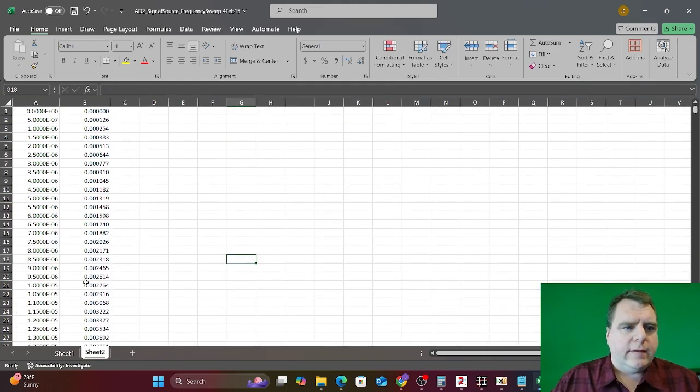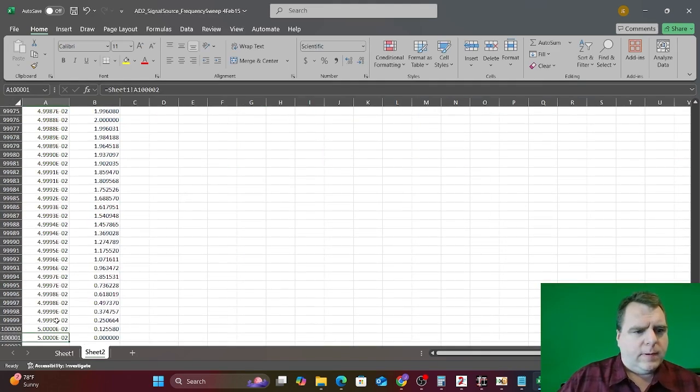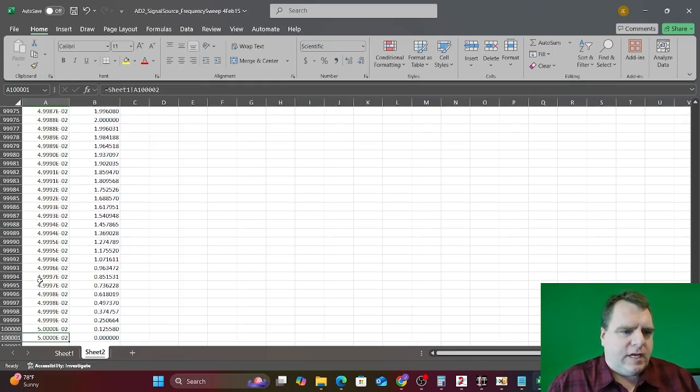Then when you look at the data here in the time column, you'll see that if you only have 4 digits after the decimal point, then you have multiple times that are the same value, and that gets interpreted as having 0 step time, and you can't have that. You have to have unique time entries in every row. So that's what the problem was, and once you fix that, then you can go ahead and run the simulation.